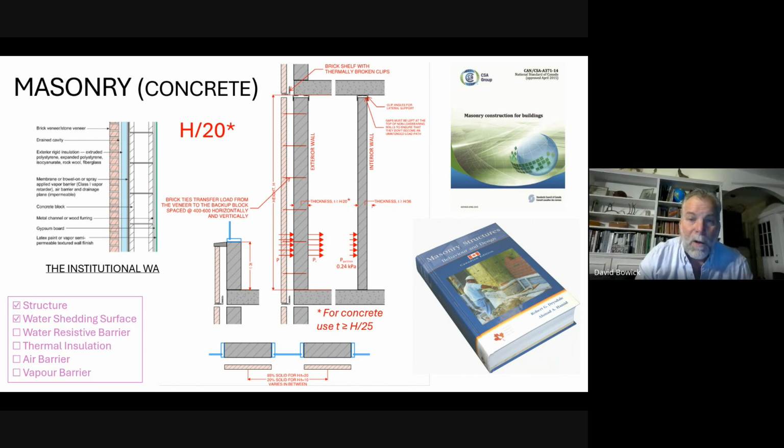If we are in a loading dock, say, where there is a big opening that can't be relied on to be closed in the event of a storm, we might design that for as high as 0.48 kPa or 10 pounds a square foot. The rule for an interior wall is similar to an exterior wall, where the approach is similar, but now our thickness is H/36.